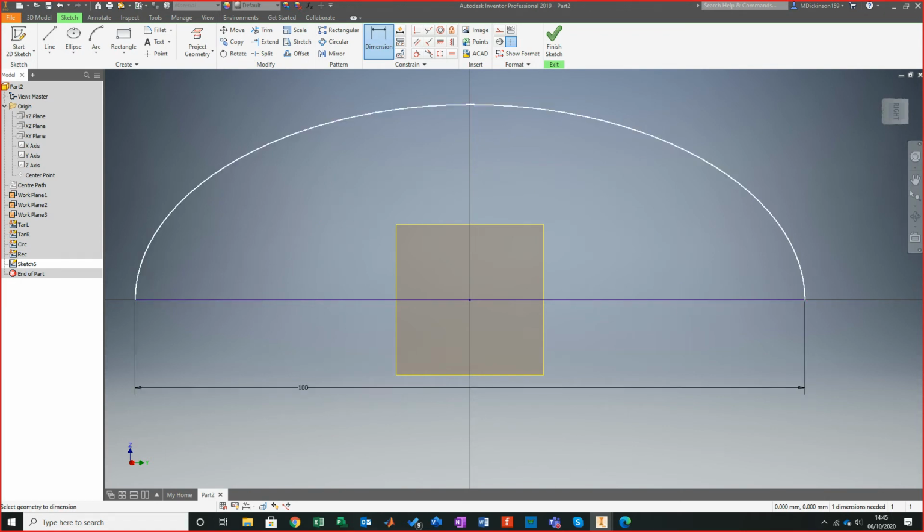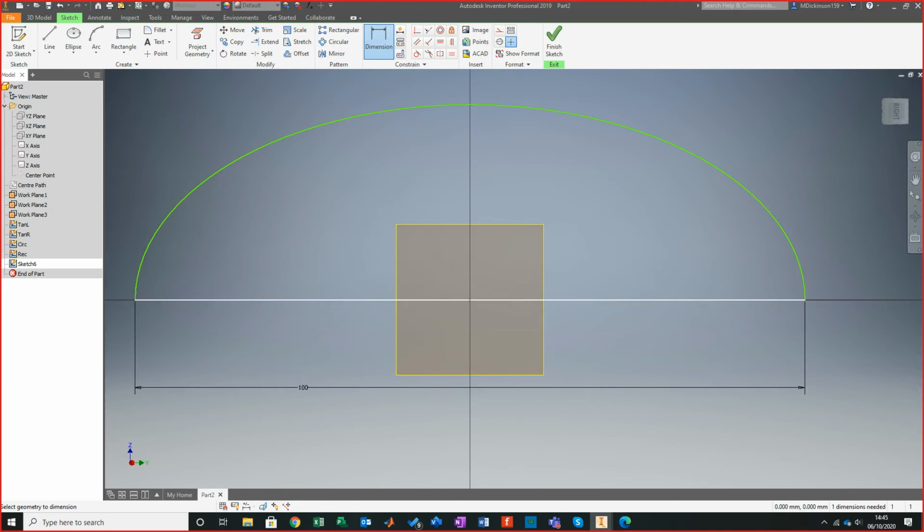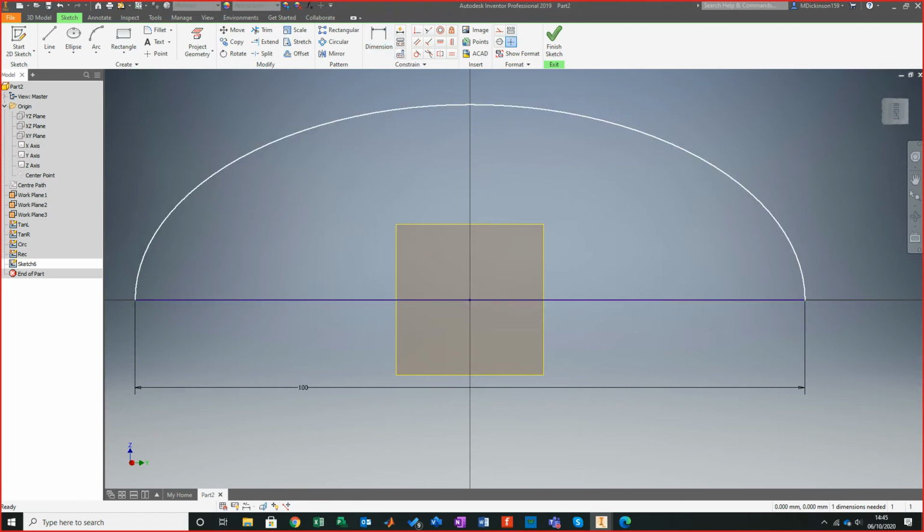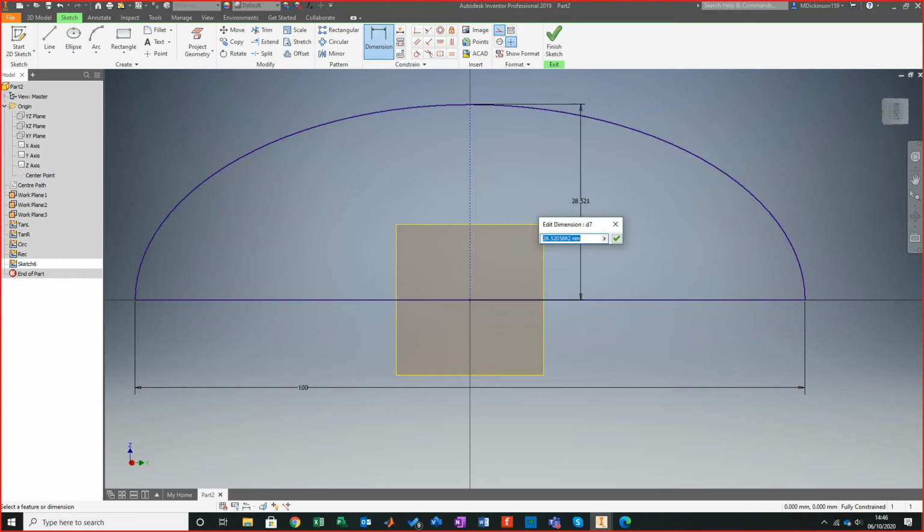And then we have a rise between here to here. Ooh, it's not giving me that midpoint there. That's very frustrating. Okay, not an issue. So what I'll do is put on a line from a construction line, and then I will push that and track it directly onto the line. So then, if I add a dimension on there, I'm going to go 35 millimeters.